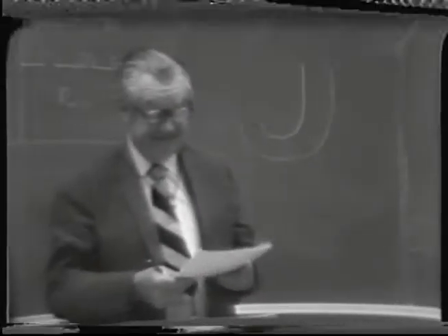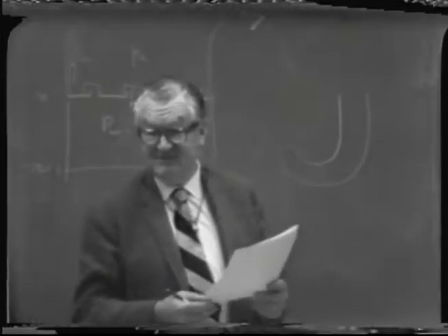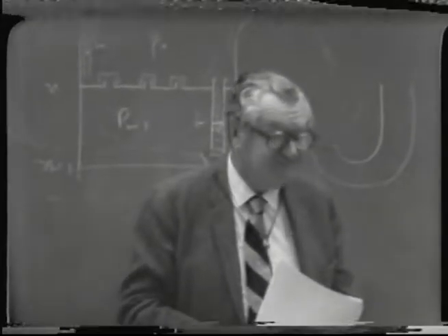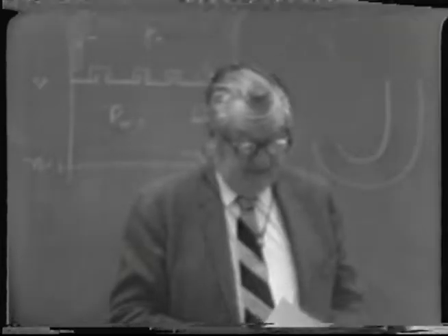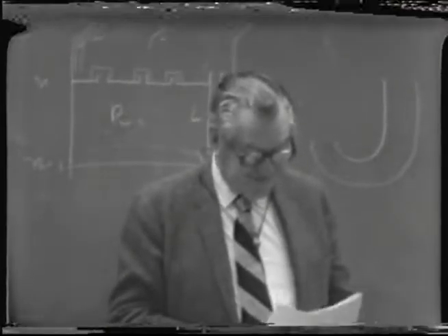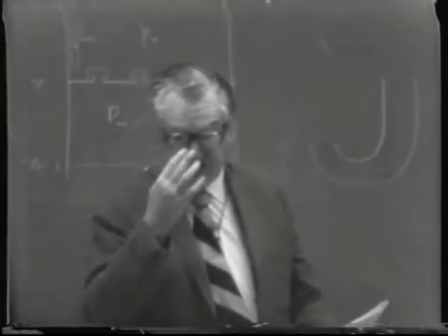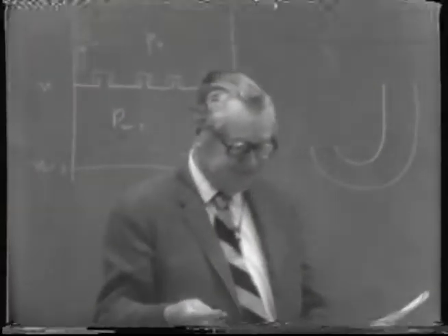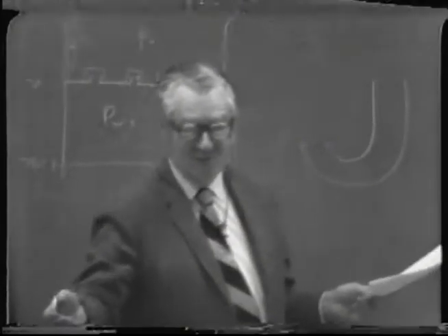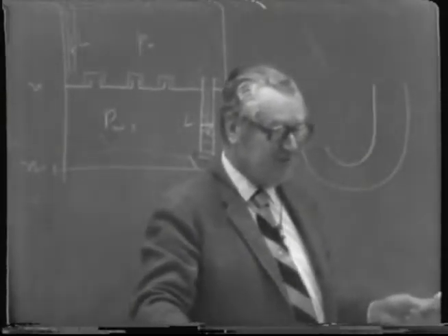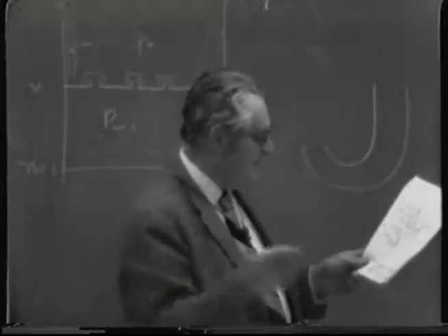Now the high pressure steam coming from the boiler, which is usually no less than 150 pounds per square inch, is considerably higher pressure than has to be provided as heat energy and flow into the still, where the base pressure is no more than 3 to 4 pounds per square inch, usually at the maximum.